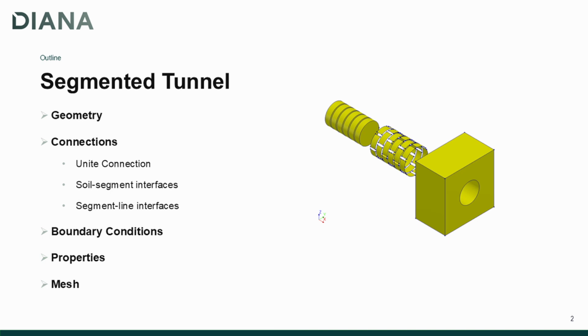After that, I will introduce the setting of the boundary conditions, including the boundary condition at the outer soil and also the boundary condition imposed by the supporting TBM. And then I will introduce the setting of the material properties.